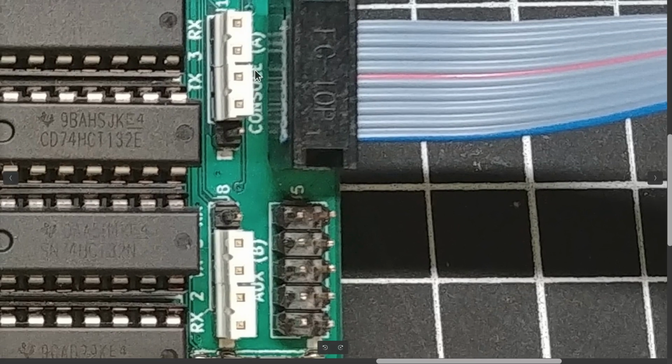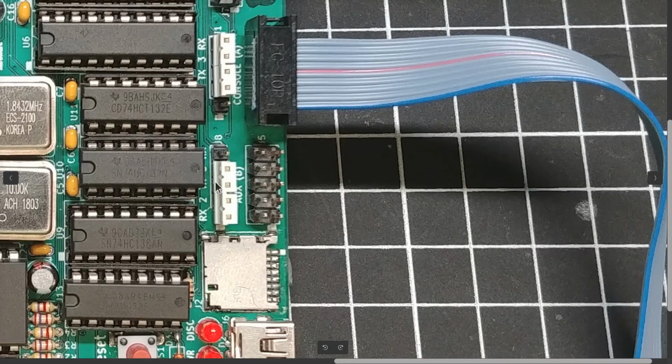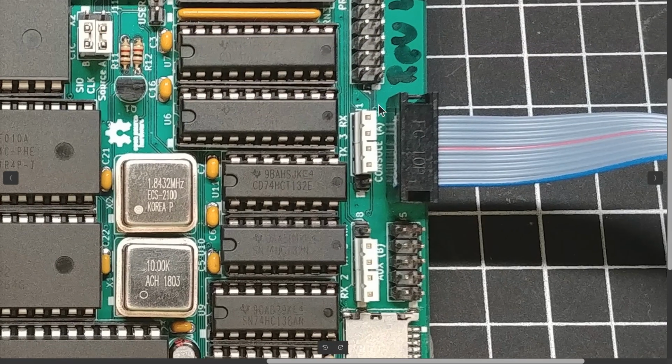Therefore, you can't take the jumpers and hook both transmit and receive to the same 2 pins, right? Only one pin will be transmit and one pin will be receive based on the physical orientation of the headers and stuff like that, all right? So you need to put headers in here. You need to put 2, and you're going to either do it like this up here or this down here. If you put it together and you can't see any output, yank them out and move them over, okay?